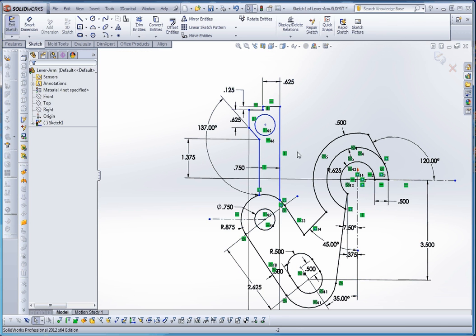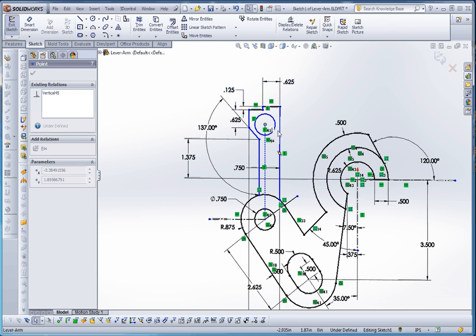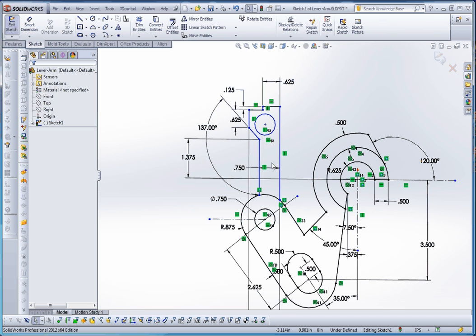You might find that convenient, so all we have to do is define this circle down here and make these two circles equal, and then we don't have to dimension this circle up here. So now that that circle is almost defined down here, probably want to get a dimension between this circle and that circle.